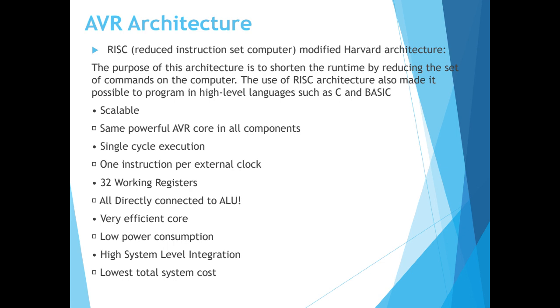About our microcontroller, which is ATmega 32 or 16, the architecture is Harvard architecture. Which type? RISC type, reduced instruction set computer type is used.